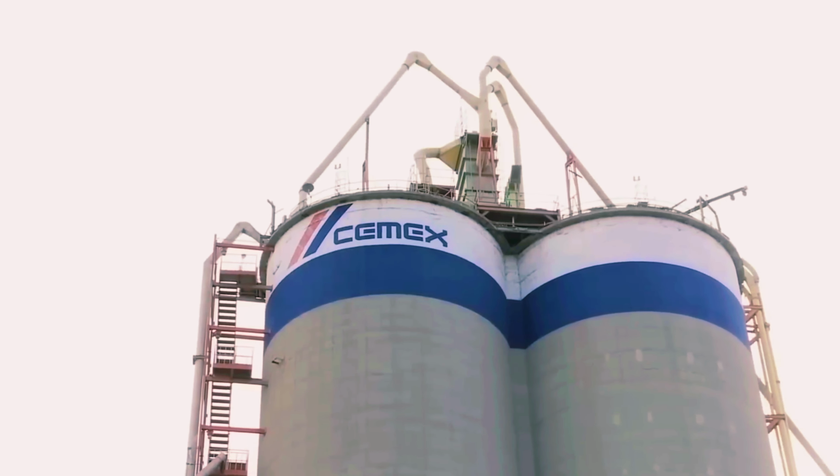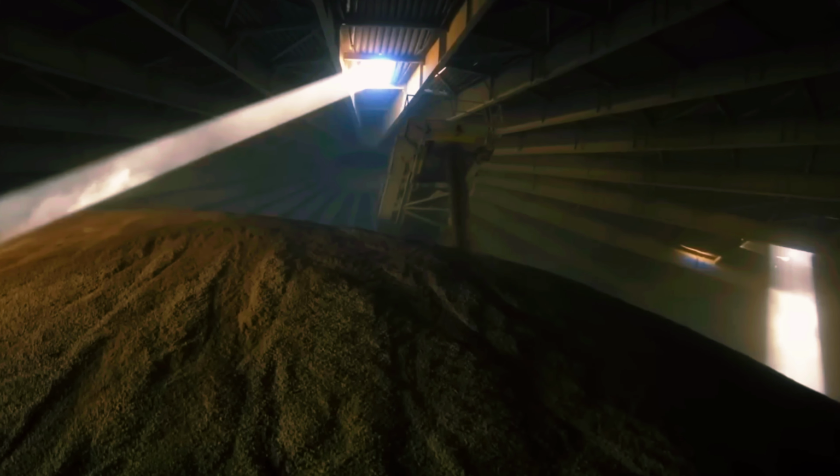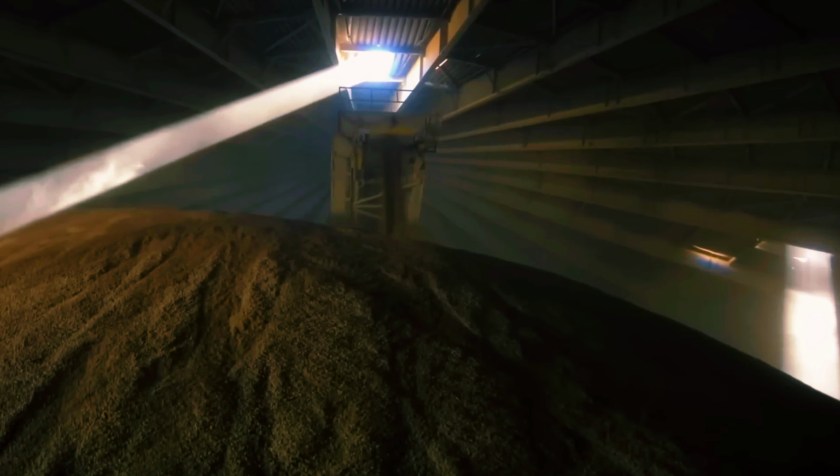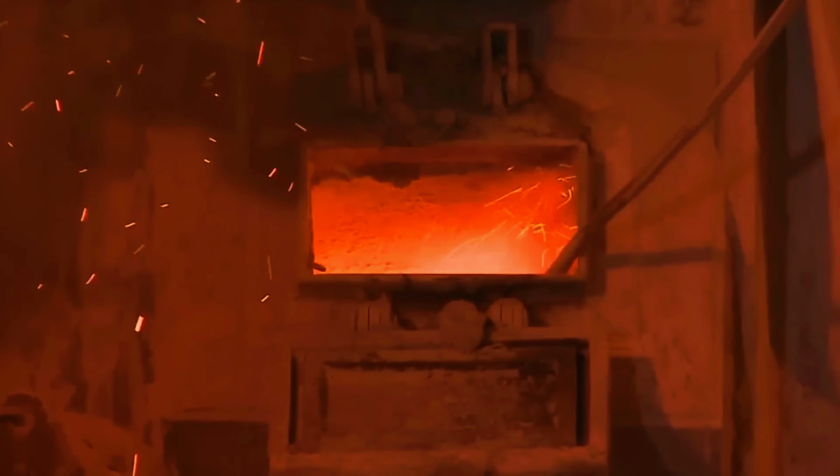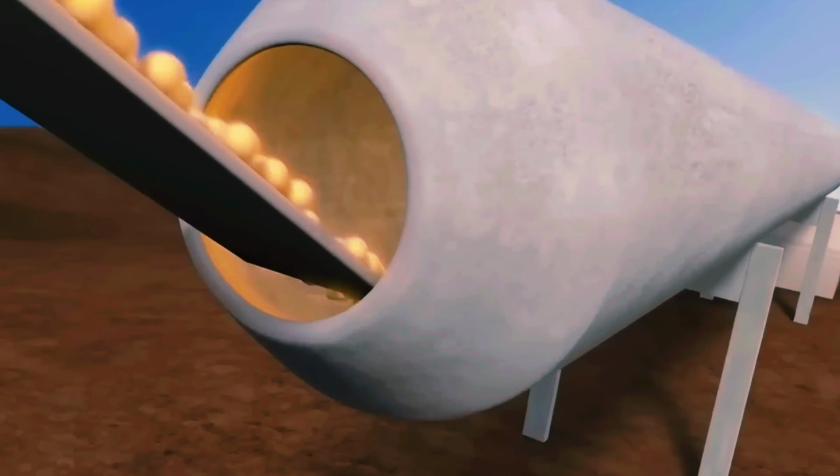The raw meal is transferred to a mill, which consists of a large rotating cylinder. Inside the mill, the raw materials are ground into a fine powder. This grinding process enhances the efficacy of the subsequent chemical reactions and ensures the uniformity of the raw meal composition. The powdered raw meal is then heated in a preheater tower where hot gases from the kiln are used to raise the temperature. As the raw meal moves through the preheater, it undergoes partial calcination, which means that some of the carbonates in the limestone decompose to form calcium oxide, lime.